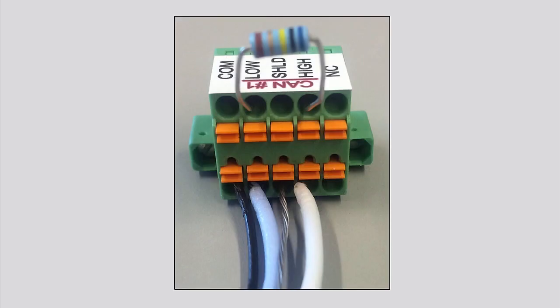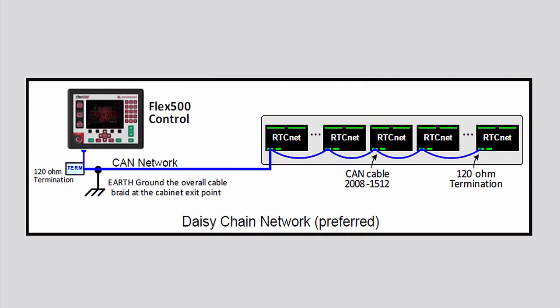For robust communications performance, the CAN cabling needs to minimize the exposed non-shielded cable section that occurs at terminal blocks. The exposed length of CAN wiring must be limited to less than 3.8 centimeters or 1.5 inches from the end of the shield to the terminal block. If multiple connections need to be made, Woodward recommends daisy chain connections.